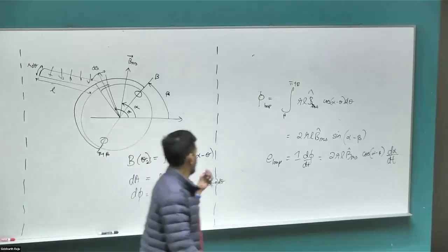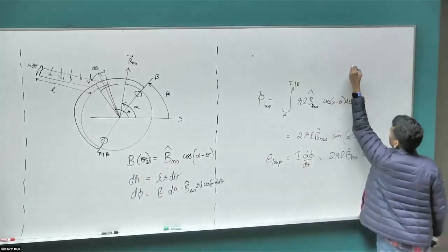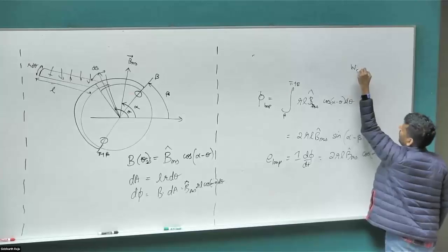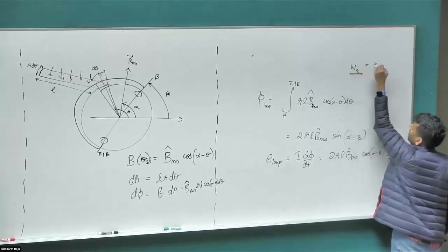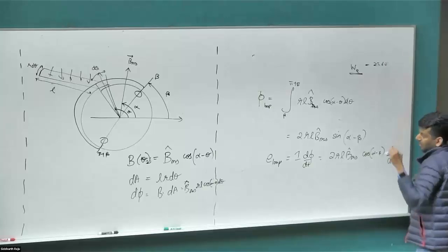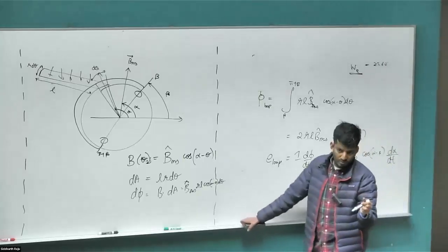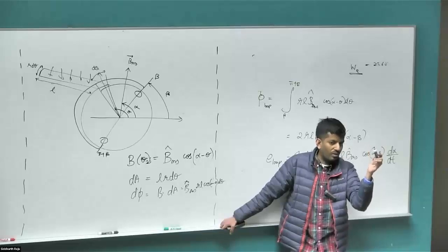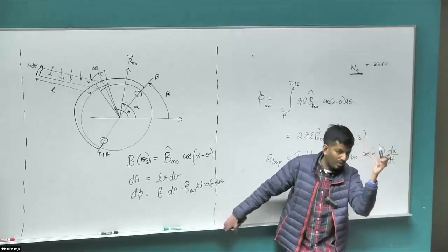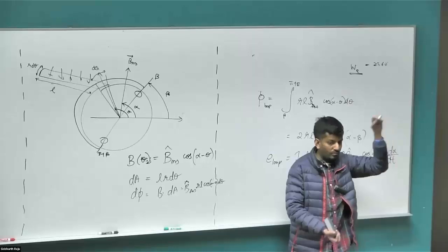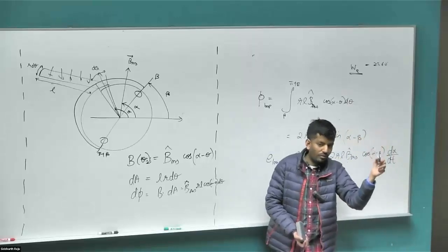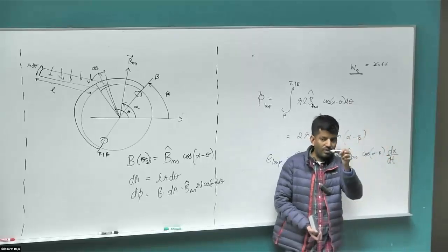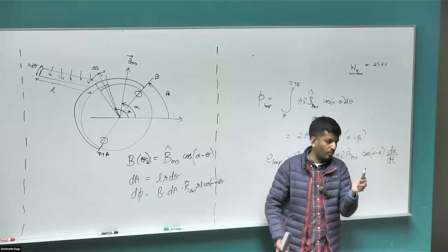Right? Because when you have stator currents and you have some electrical frequency, let's say 60 Hertz, 2 pi times 60, and you plug in those 3 currents into the space vector transformation, you would have ended up with the formula e power j, 3 by 2 times Im e power j omega t. And that omega would be same as whatever the electrical frequency is, the rate at which the sine wave changes. Because if we start from some value and end at the same value, the space vector should have completed a full rotation.